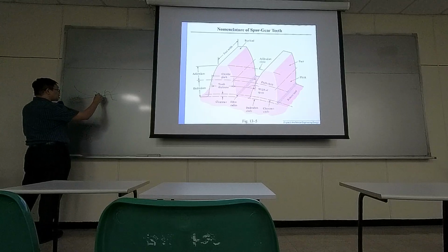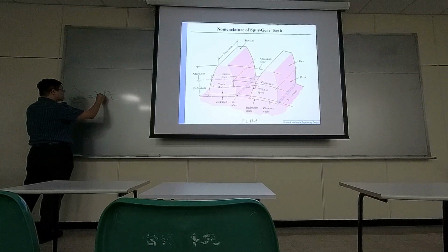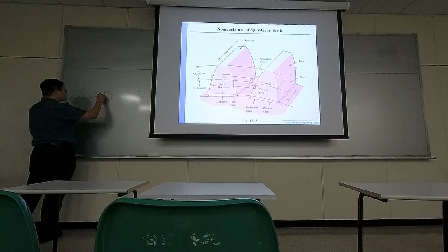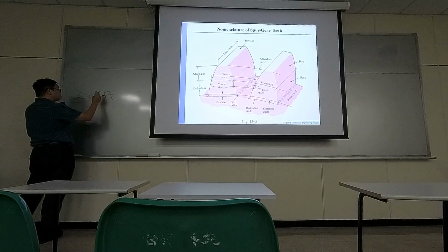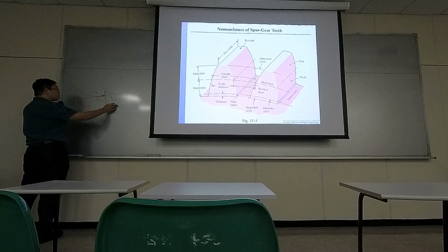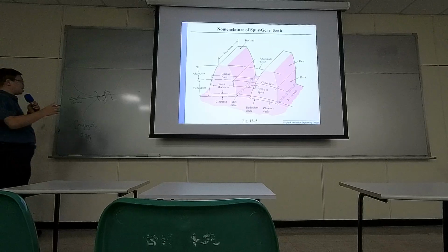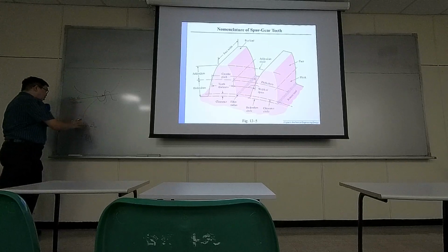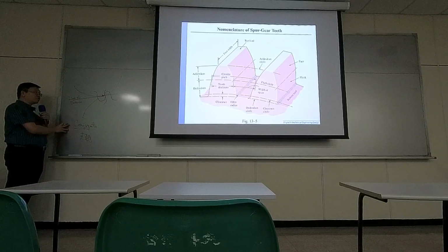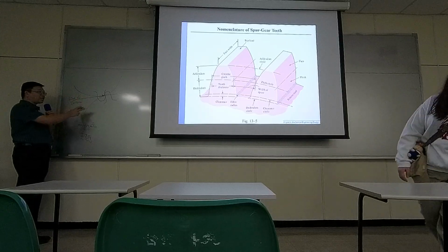So it's like from one side of the gear, there's a pressure applied from this side to the other side. Okay? So the profile of the teeth is so well designed so that when gears are having this conjugate motion, this pressure stays on the line.